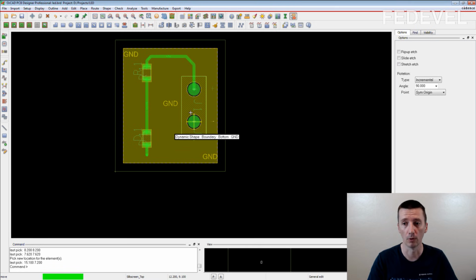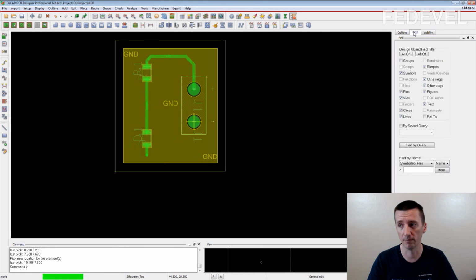If you would like to move the text of the components, you need to use a filter. Have a look. Now if I try to move only the text, it always selects all symbols. See, go here, find, select this off, and just check text.